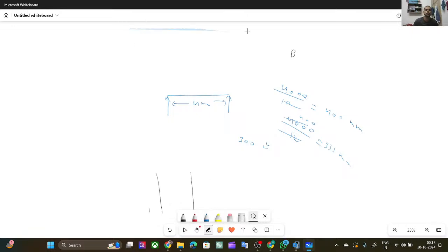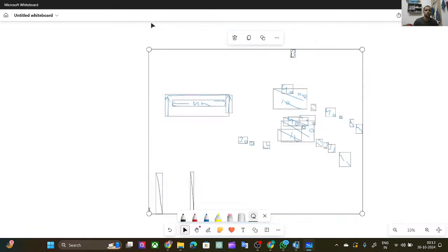First delete it. So it is my plot, and there is a door. Okay, and door spacing will be nearest 2 meter. Okay, 1 meter this side and 1 meter this side. So if I will not make any column in this side, I will make the first column in this side and in this side. The column spacing, center to center on the inner sides, will be 2 meter, because my door size is 2 meter.